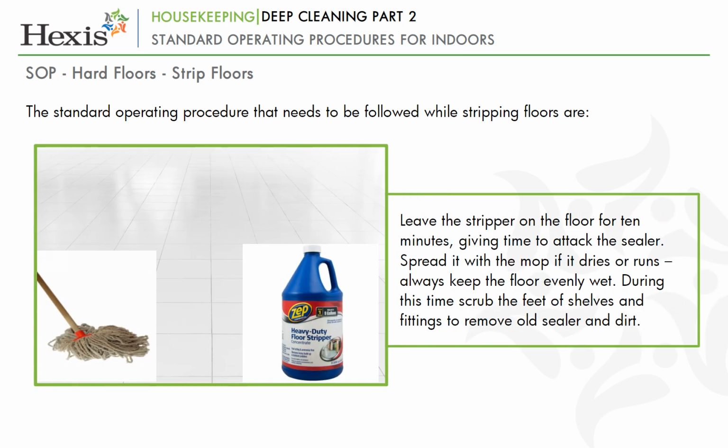Leave the stripper on the floor for 10 minutes, giving time to attack the sealer. Spread it with the mop if it dries or runs. Always keep the floor evenly wet. During this time, scrub the feet of shelves and fittings to remove old sealer and dirt.